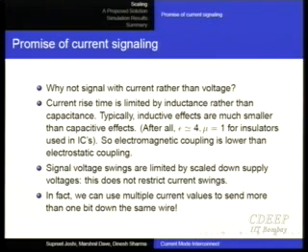What happens is that the wire delay, the RC time constant, remains the same, but the delay refers to a voltage change which is much smaller now. Therefore, the delay becomes smaller by the factor V divided by delta V. Okay? So, same RC time constant, but now you are charging over a smaller voltage difference. So, as a result, it happens quicker.